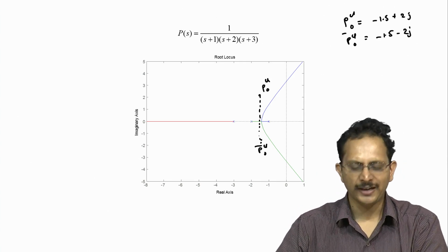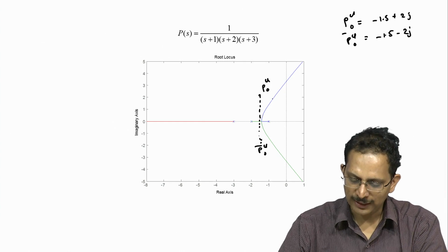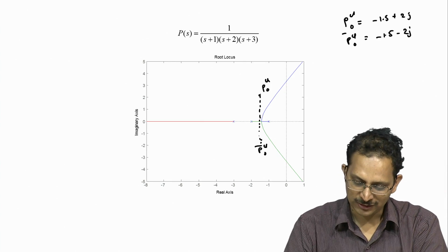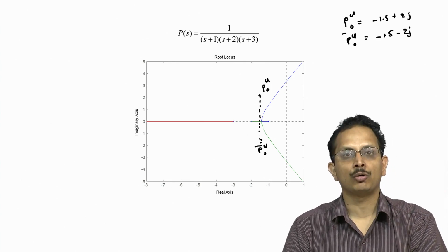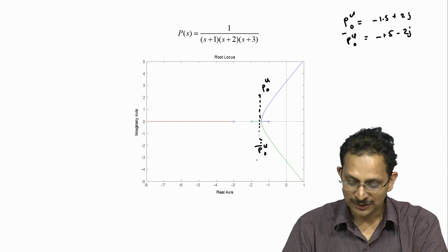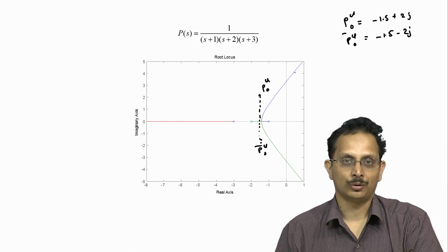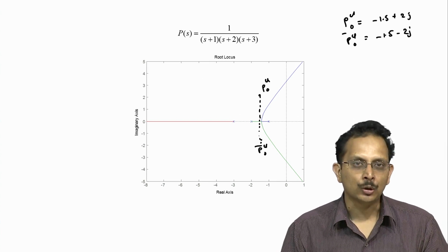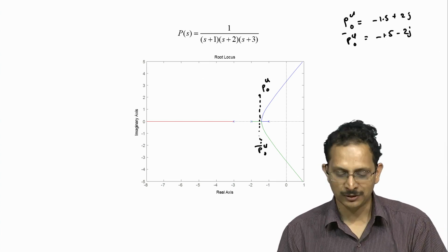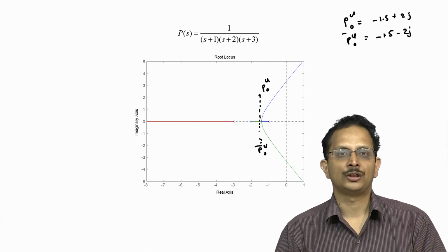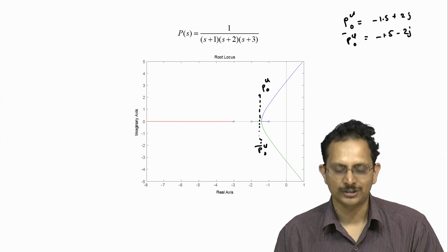So, if I were to change the gain k, the closed loop poles can vary along these particular curves. However, for this case the location where we want our dominant closed loop pole to lie is outside of the root locus. So, it is not possible to use a simple proportional controller as we did in the previous examples in order for us to realize this particular pair of dominant poles for our closed loop system.